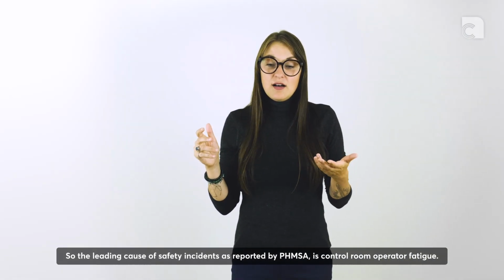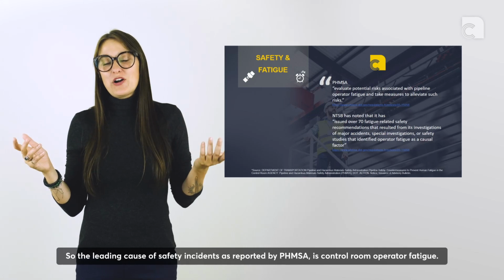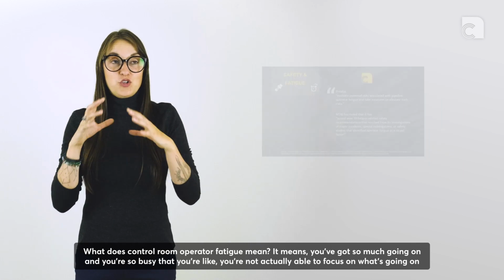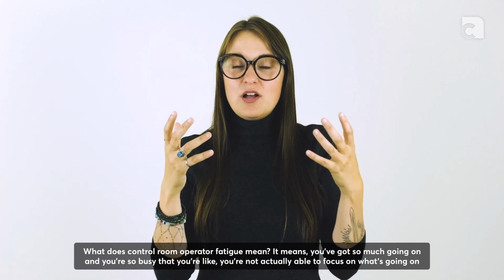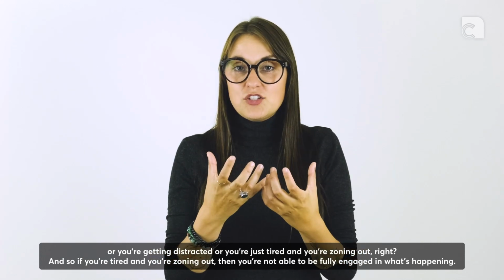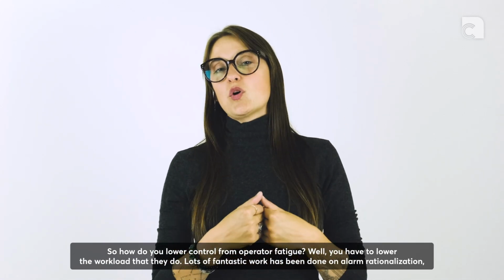The leading cause of safety incidents, as reported by PHMSA, is control room operator fatigue. What does control room operator fatigue mean? It means you've got so much going on and you're so busy that you're not able to focus on what's going on, or you're getting distracted, or you're just tired and zoning out. If you're tired and zoning out, then you're not able to be fully engaged in what's happening. So how do you lower control room operator fatigue? Well, you have to lower the workload that they do.